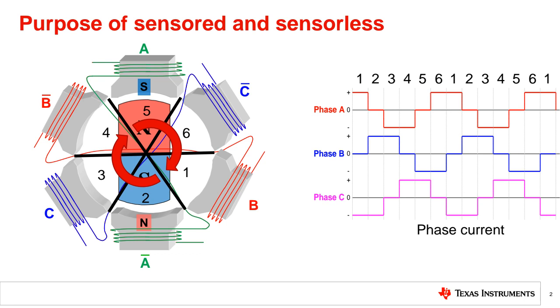Lots of times you hear from me or another professor in motor applications, we say it every time: speed means voltage, current means torque. If you estimate speed, then actually position, you know the position is the 1 over s, the integral of the speed. So you need to know the voltage of the armature. It means that if you want to estimate speed, you need to know back EMF.